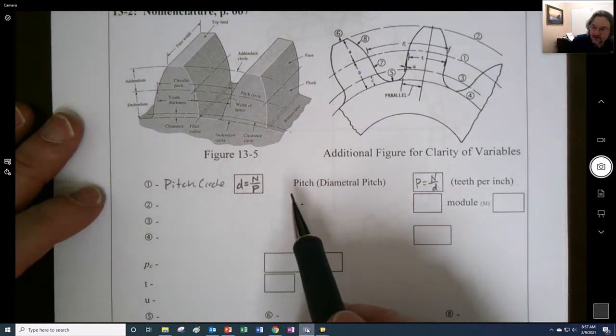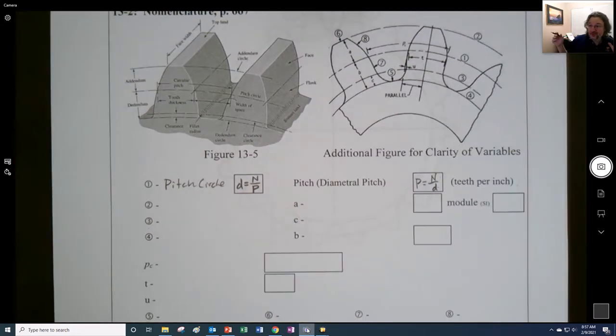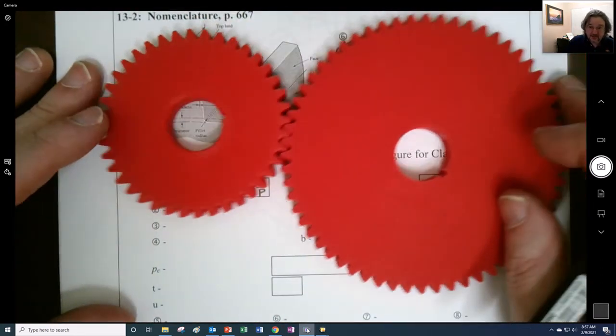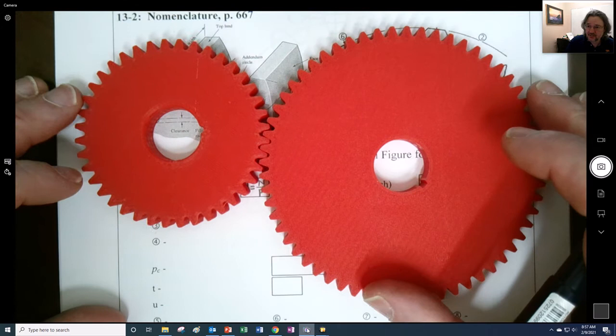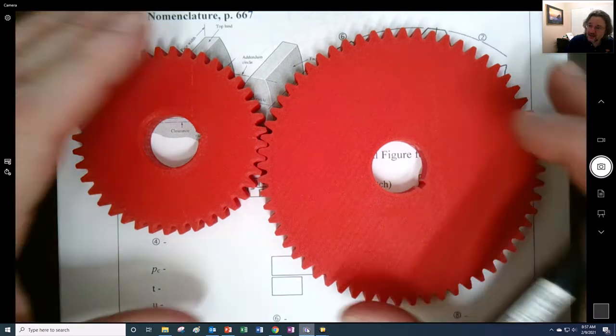But quite often you might look up in a book, you want to pick out a certain gear, and you say, well, I need to have 20 teeth connected to 40 teeth. I'm not sure if that's the right number right here. I should probably count these. And then you pick out of a catalog what pitch. That'll determine the diameter, right?